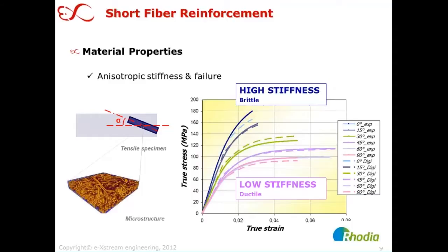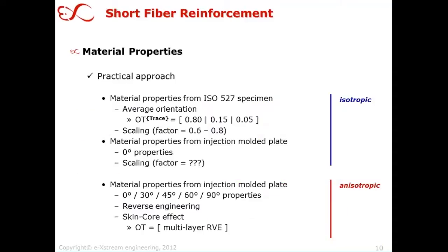And so this is exactly the challenging situation, because all these different curves that we look at here on the slides must go into one material model in principle. So this leads us to the question, how are the material properties from these measurements used in simulation in a practical approach? And if you go to companies these days, some will want to tackle this in some anisotropic material model formulation, but what you quite often find is that there is some straightforward approach, which of course is nice